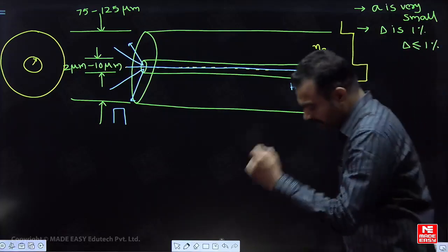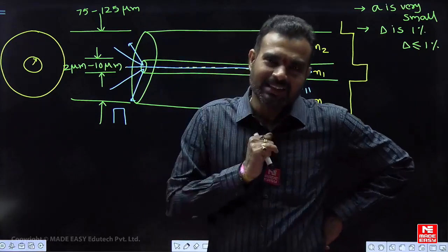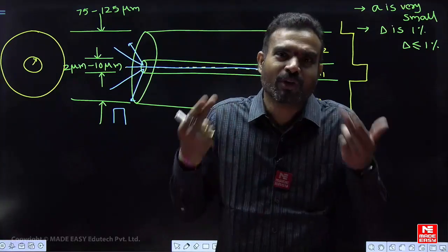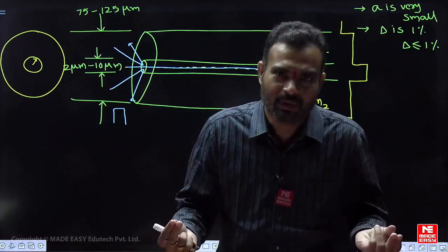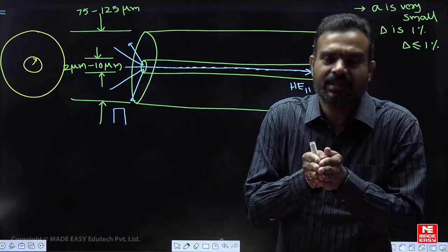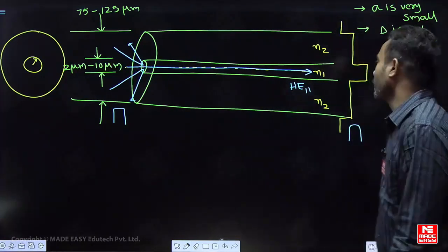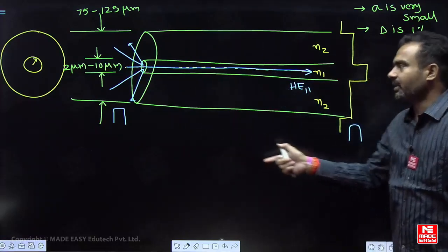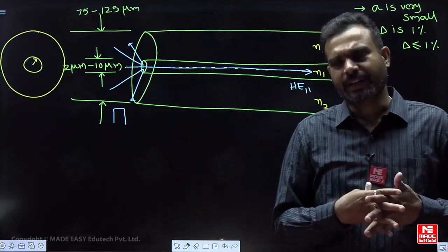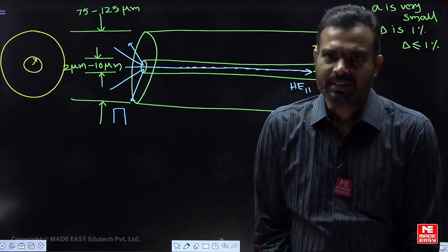Okay, what we study in communication systems, in PCM, in guided transmission: when you send a pulse, a rectangular pulse is transmitted. After traveling some distance, the pulse will spread due to the non-linear characteristics of the channel. Because of that, the pulses are going to interfere with each other, and the pulses are going to have ISI, intersymbol interference, which creates errors where the probability of error increases.